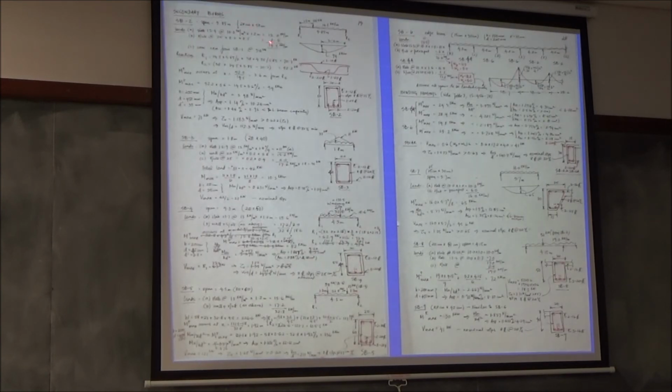Then we did all the secondary beams. You see all the calculations. This is how typically it is done. This training I got in Delhi, where we had to do it ourselves, all the calculations, no computer. And you have to show the loading diagram, you have to show the bending moment, you have to do a quick calculation of the loads, find the reactions, find out where your moment is maximum. There's a concentrated load here. That's where your shear force is minimum. You understand? Then Mu by bd squared.